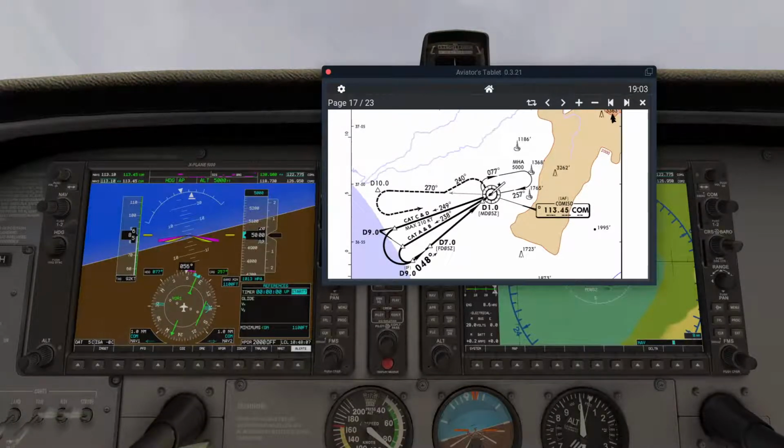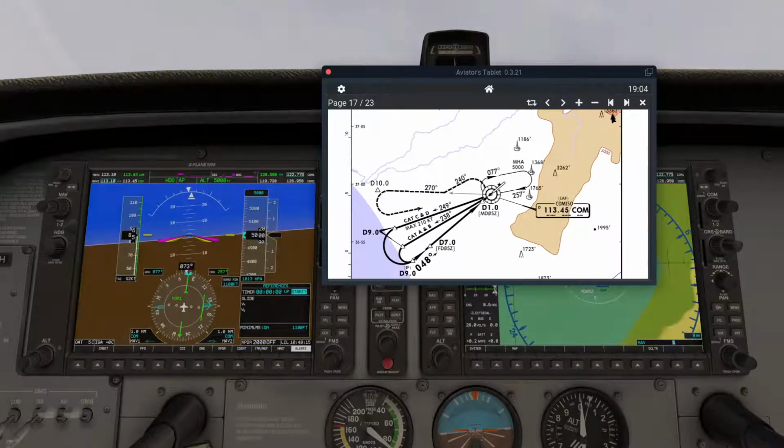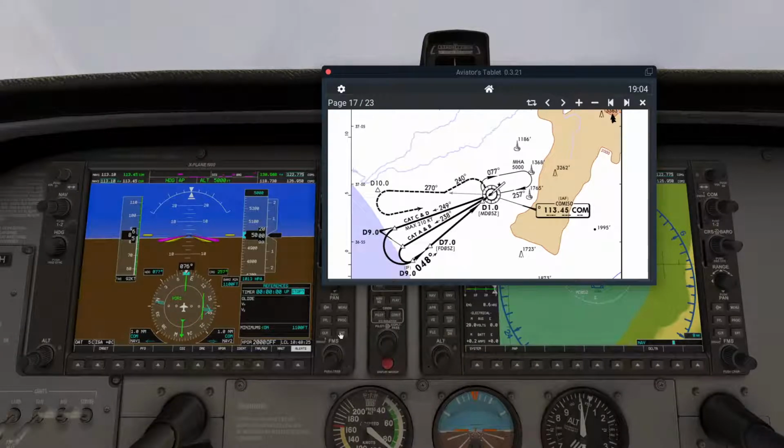Whichever is later, we can check the time and start the chronometer and timer. You can see we are looking to abeam the station, and also wings going to be level. Start the time on heading 077, which is the outbound leg of the holding procedure.